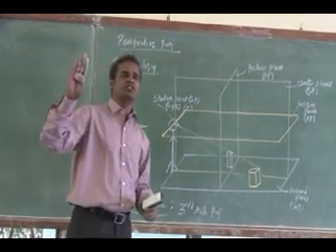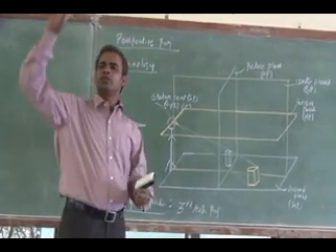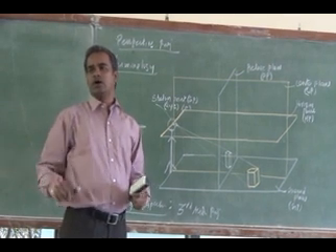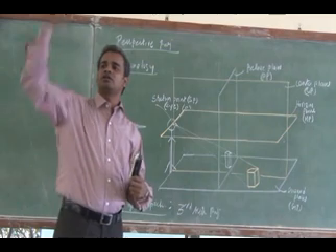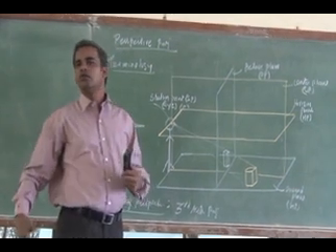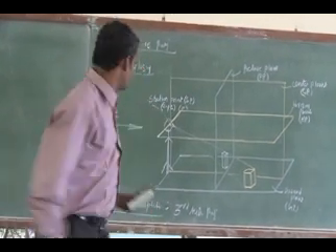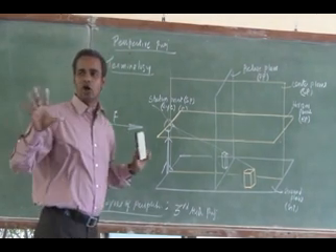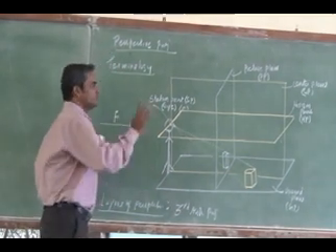You know first angle projection. In the reverse, in first angle projection, I will have the front view on top and the top view below the front view, right? But in third angle projection, the top view will be on the top, and the front view will be below that, right? So the whole setup will try to represent the top view, right?